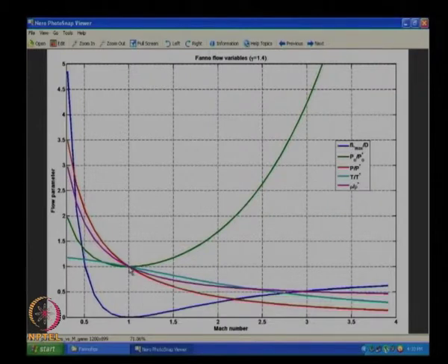This is coming from your energy equation and momentum equation from basics, we did this in isentropic flow at the beginning. So the same reason: when the flow is accelerating, pressure and temperature will drop, and when I look at it from supersonic flow, it is going to decelerate to M equal to 1, so pressure and temperature will increase. They are all going in the logical direction. And density is going to be something in between, and you know the pressure sensitivity is much more than temperature sensitivity, so density does the remaining thing which compensates for P equal to rho RT, that is how it works. This is the case for gamma equal to 1.4 that I have plotted.